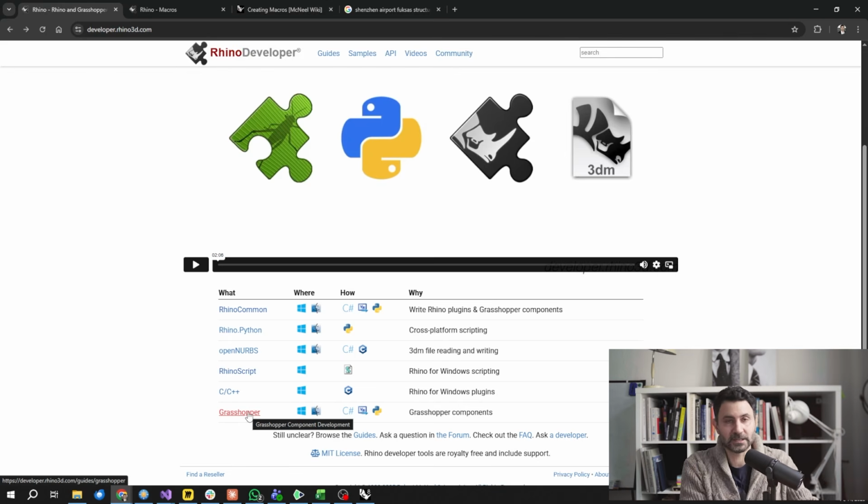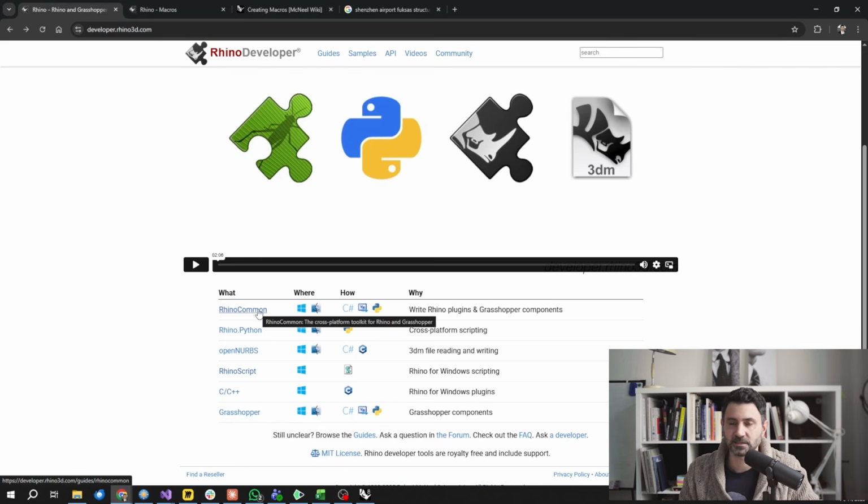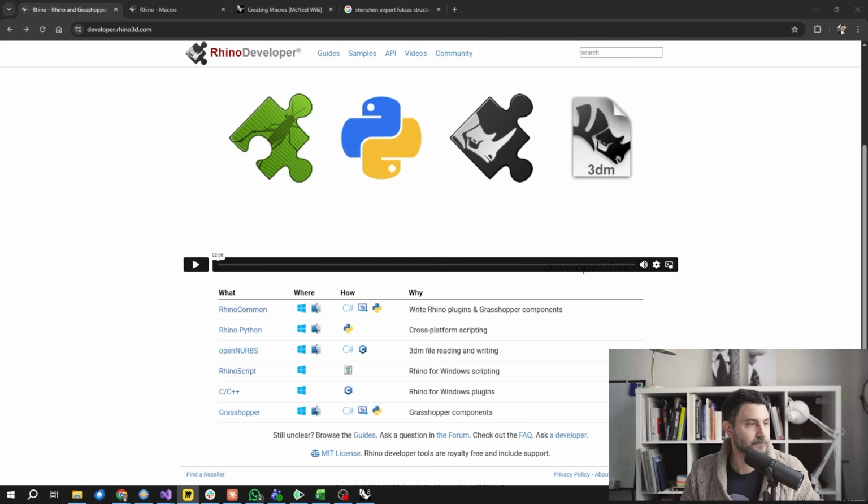you create them completely in Visual Studio as a project, and then as the last step you go and create this full C# or C++. I mean, C++ still works, and it's the fastest possible solution. But I switched to C# because it's managed and much easier to control, and you have some libraries that you can use and so on. So that's the way. This Rhino Common API will give you full access to Rhino geometry, documents, user interface. You can do basically everything that a McNeil programmer can, right?